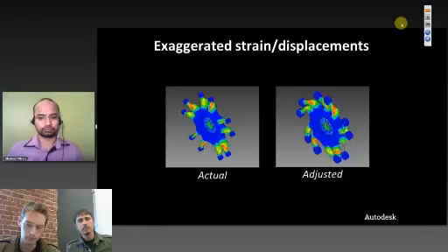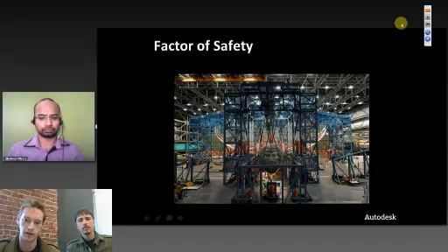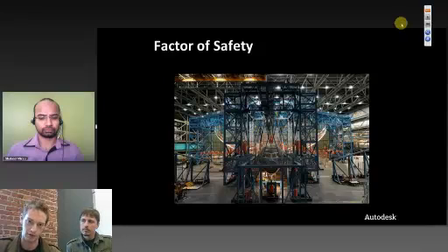So next up is factor of safety. So factor of safety is the amount of overbuilding, you could say, that you do for a piece. So when you're building something, you don't want to design it such that the highest load that it will ever experience is the yield stress, because it's possible that maybe somebody a little bit bigger than you expected, or a slightly stronger force, a little bit bigger earthquake, something like that comes around, or that your machining isn't exactly perfect. You can only say this with exactly perfect machining at a factor of safety of 1. So you often give a bigger factor of safety. You say a factor of safety of 2, meaning that you design it to be essentially twice as strong as you expect it to need to be.